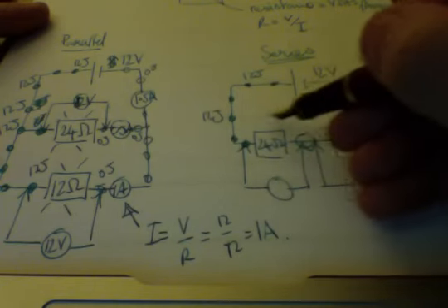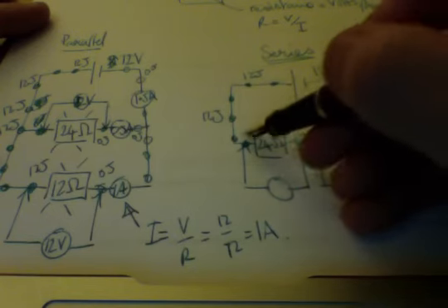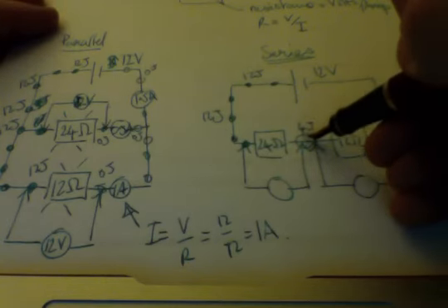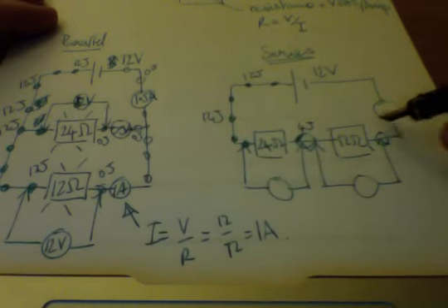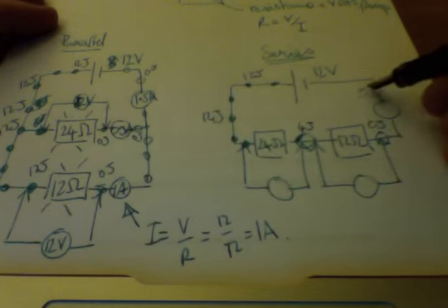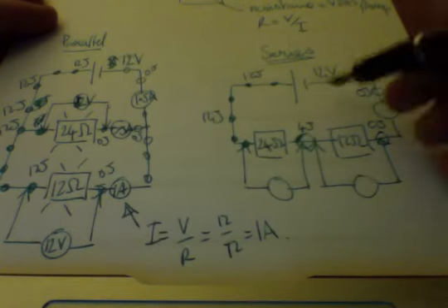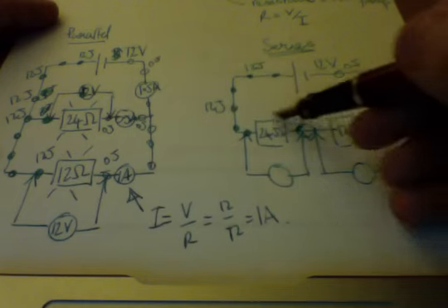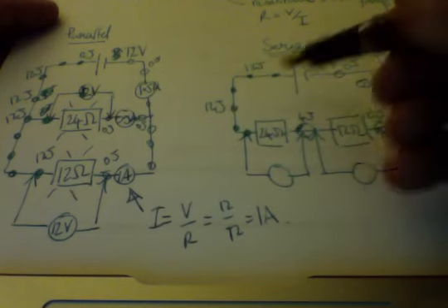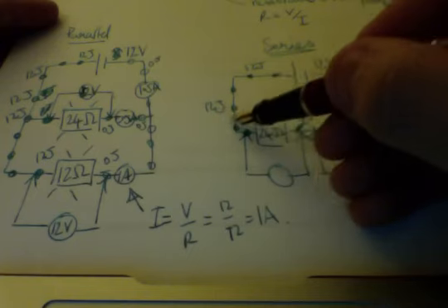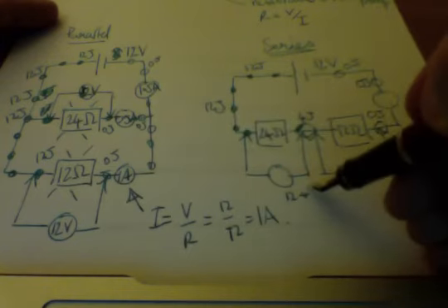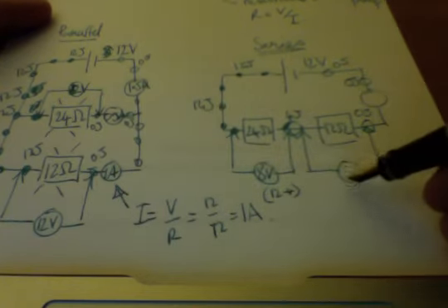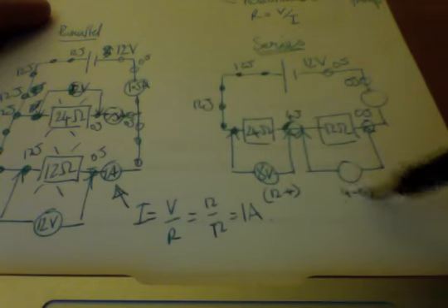So if we've got used up twice as much, then 8 joules must be used up here, leaving us with 4 joules remaining before it comes out and is left with no joules. And it goes back to the battery with no joules. Okay, it's a little tricky there at that time, but you've got to look at the ratios. Given that's the case, the difference between 12 and 4 gives us 8 volts. Obviously, the difference between 4 and 0 is going to give us 4 volts.